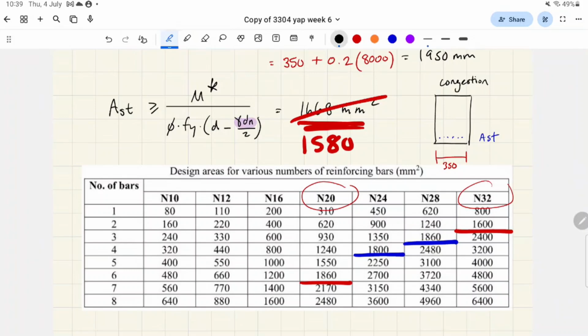Anyway, so we know that going too low in terms of diameter and having too many bars is bad. Why is too high bad as well? This is another construction kind of problem. Is that too much space between it? There's actually no regulation for having too much space as long as the cover is correct and the spacing is big enough.